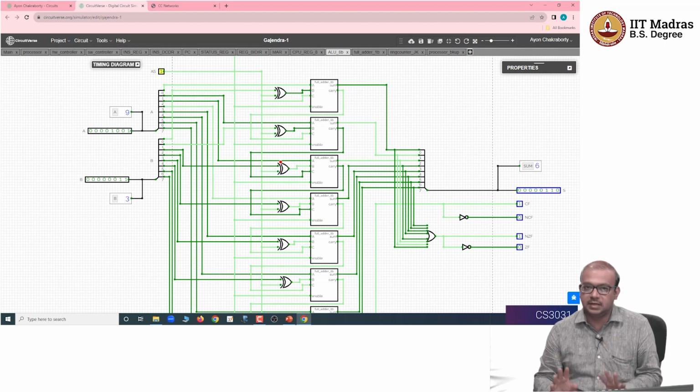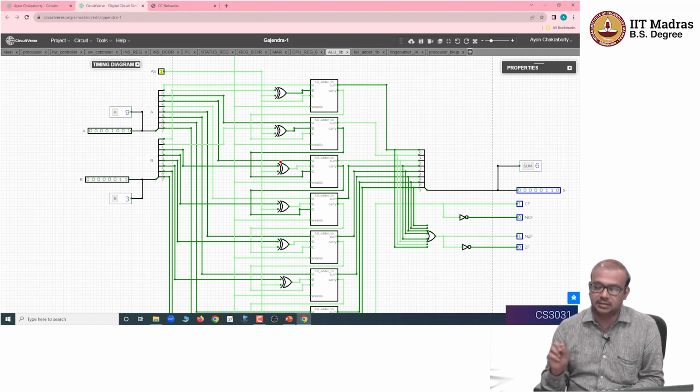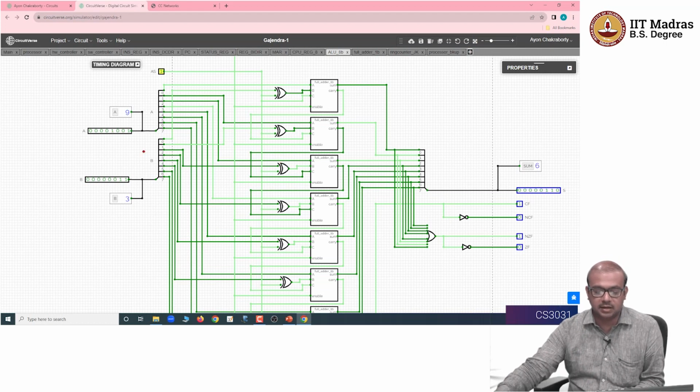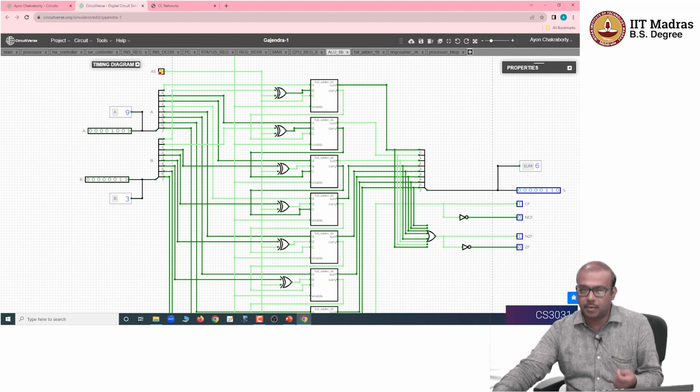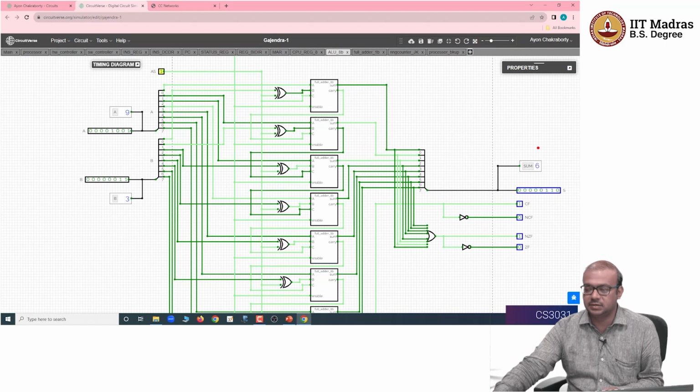Everything has been shown: how exactly the subtraction operation works, including the circuit, and how we integrate the subtraction operation on a regular full adder using that XOR gate. So 9 minus 3 is 6, and if I activate A is equal to 1, which is the control input for operation selection of the ALU, this becomes 6.